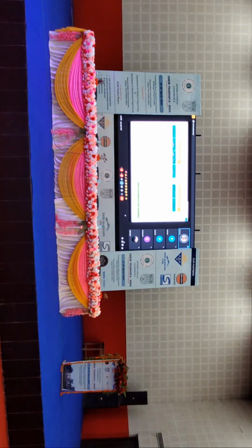Next is the full or the strong hybrid electric vehicle. Whatever we have seen in the mild, we have additional energy and power, and the efficiency improvement is around 20 to 30%. However, in this case, if we are going from left to right, the size of the battery is increasing, the size of the motor is increasing. If both are increasing, then we have to accommodate them in the available space. So we have to downsize the engine. The engine size reduces and the motor and the battery content increases.